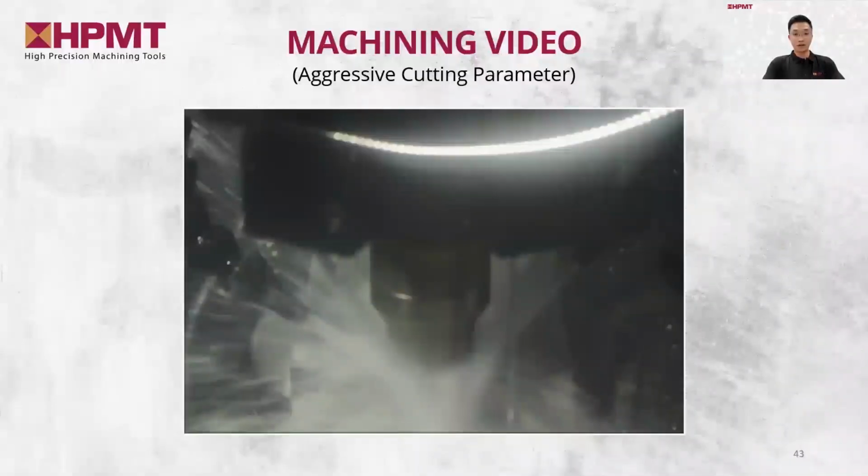As you can see from the video, machining Inconel 718 material requires a lot of coolant due to its tough and high strength properties. It will generate more heat than usual during the machining process. So the purpose of using the flood coolant here is to keep the temperature down.